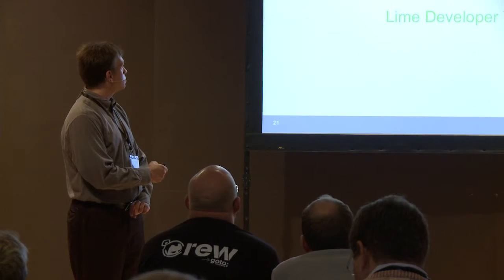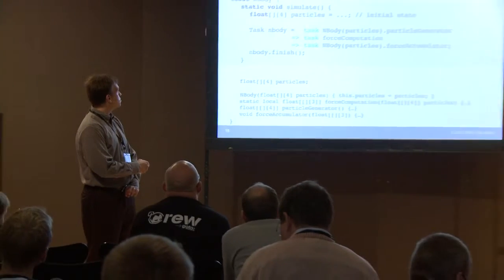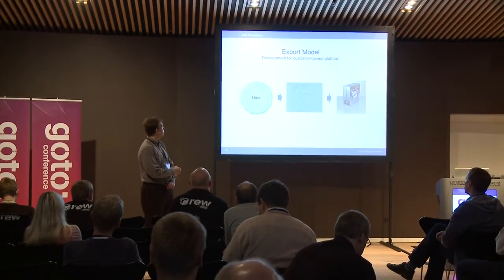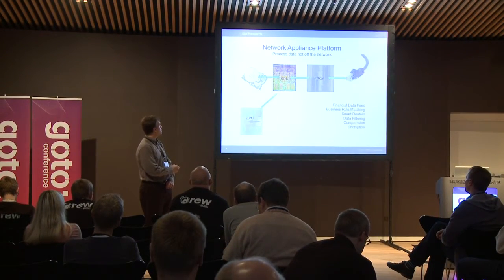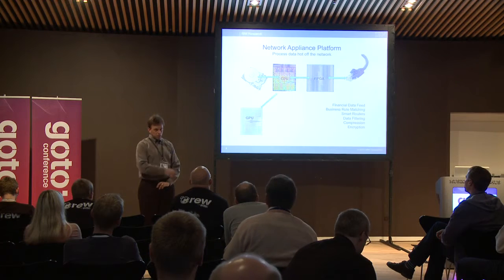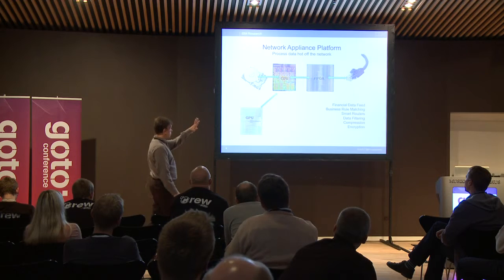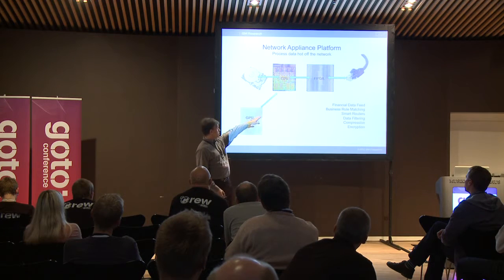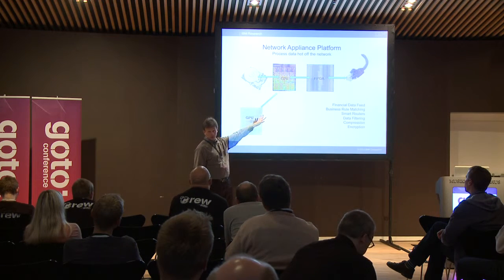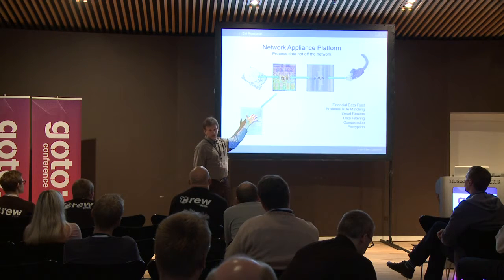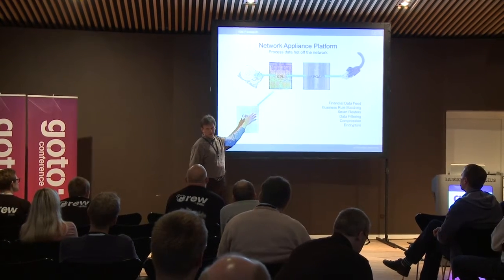Yeah, so of the scenarios I started with at the beginning of the talk, my personal opinion is the one that's most attractive is network attached. In this case, in the common case, all the computation will be done in the FPGA. I guess in theory, you could cut the cord and just detach the FPGA, but in practice, it's usually attached to a host because you have to boot the device and load things like that.